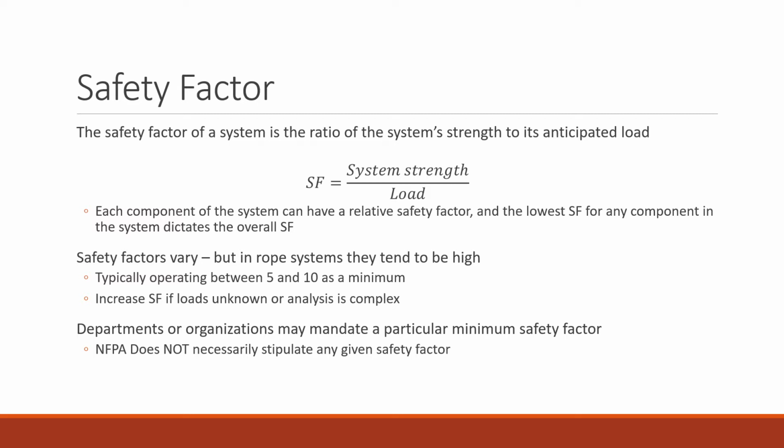So safety factors can vary. In aviation, we're looking at safety factors somewhere like 1.1. I hear some rocket construction is done at like 1.05. Kind of crazy tight safety factors because they're using a lot of computers and precision materials, being very clean about it. A lot of civil engineering work is in the range of like 1.7, 2.5, things like that. A little bit higher. We're accounting for how little we know about some stuff.